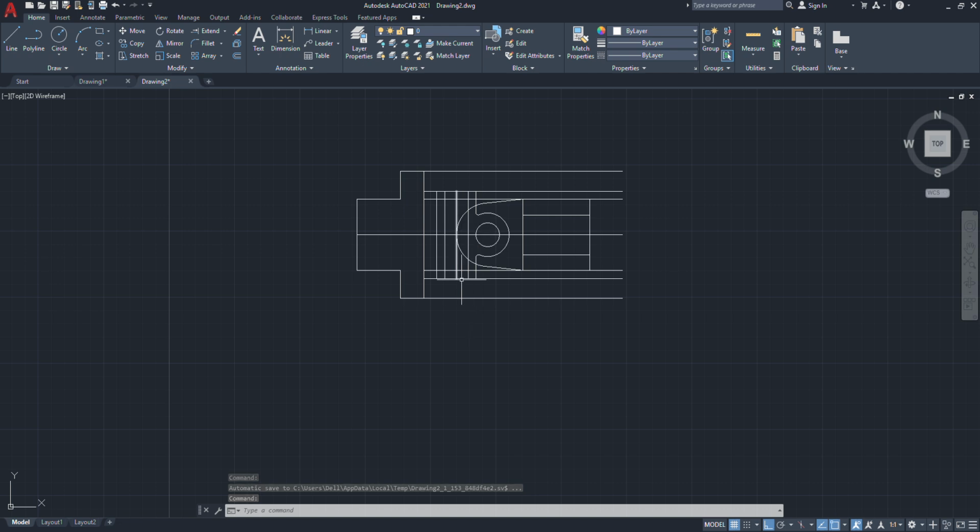This axis, 24 mm, is this line. Okay, so we have to offset this line to 24 mm, this line center, this is the axis, towards this side. Offset through 24 this line towards this side. Okay, so this is that line, so we will extend that line to meet this line and this line. Okay, unwanted portions we will trim now.